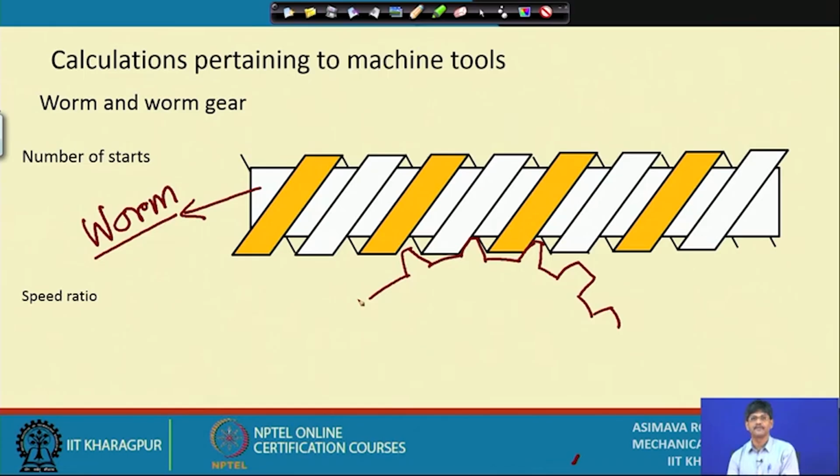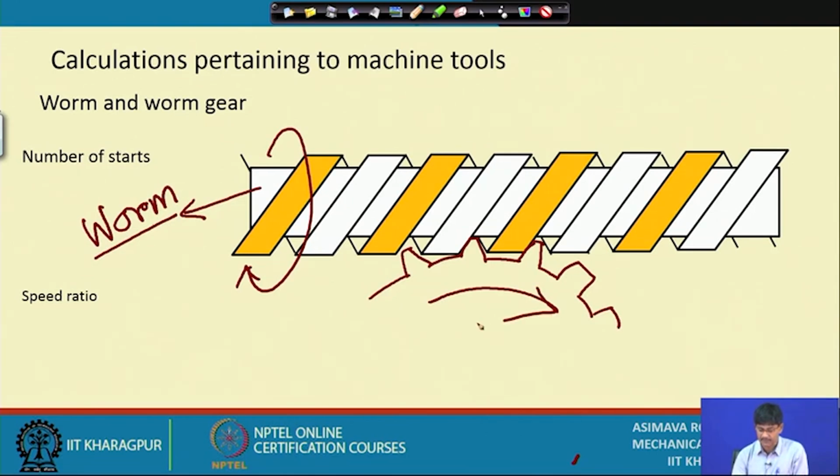Like that, which means that if the screw is rotating, the worm gear will have to rotate with it. In which way? That is, tooth by tooth, this particular helix, as it is slightly inclined, these points will be coming sequentially and they will be pushing the toothed wheel to one side, and this is called the worm gear.